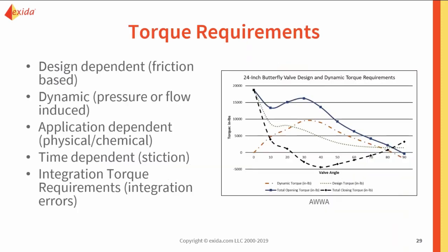I mentioned torque. There's multiple different torques. Yes, there's the torque that you need to work the actuator, work the valve, but there's more than just that. There's breakaway torque. We also have your dynamic torques. We're going to look at the friction, make sure you're in the same application, the same operation, make sure it's time dependent, whether you have low demand or high demand, making sure that you have that apples to apples comparison.